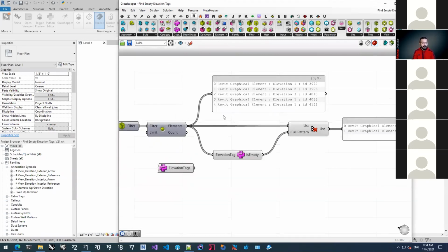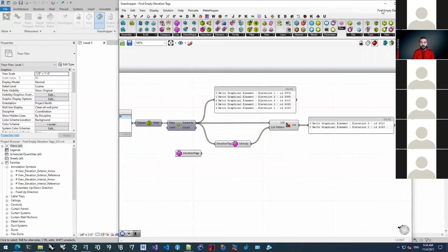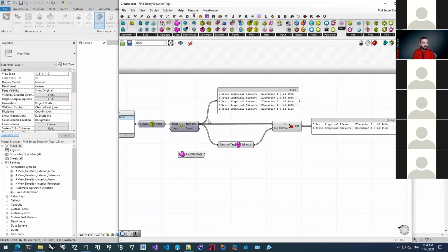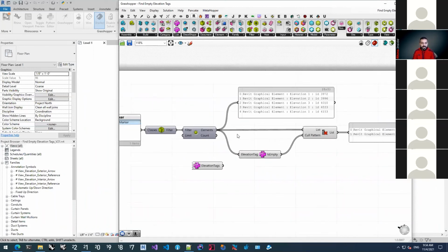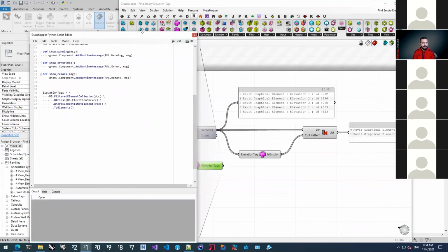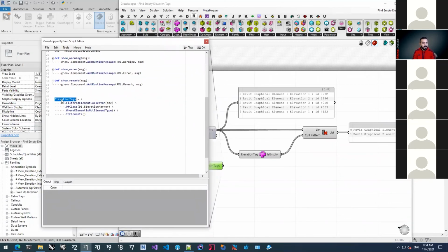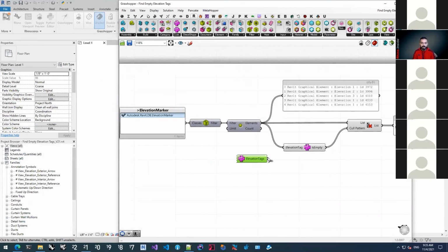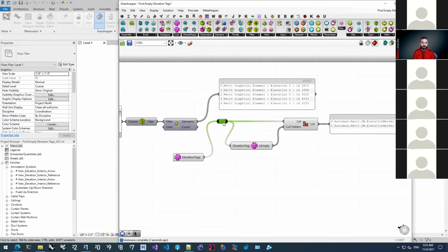Revit API has methods to do this a lot faster. As an example, I'll show you an example after this to create a custom advanced filter. But basically, I had this example placed inside that definition, that you can see. That Python scripted component that I have collects elevation tags, that DB filtered element collector of class, where element is not type, to elements, and all of that is passed to the admin. So if I use my collectors from Rhino Inside Revit or this, it really doesn't make any difference, right? We can swap these two very easily, and the result will be exactly the same.